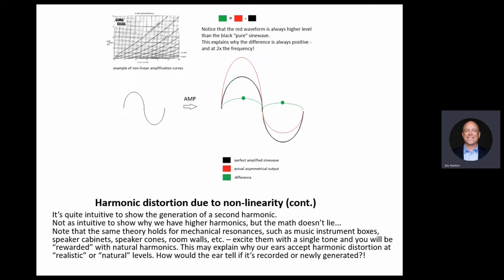From a single peak, we got 2 peaks. Second harmonic. Very easy to see. Most single-ended circuits with nonlinear devices will show a second harmonic. This is the reason, because the nonlinearity creates this kind of distortion.